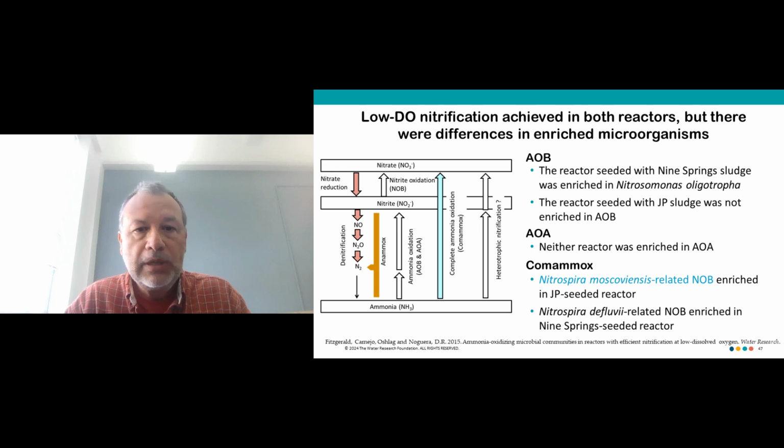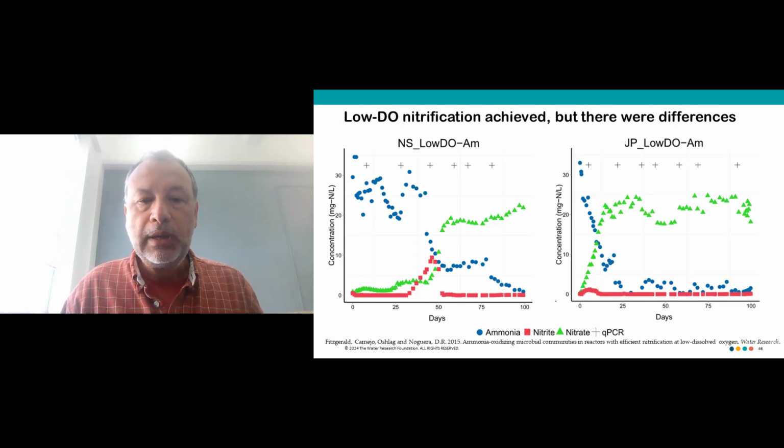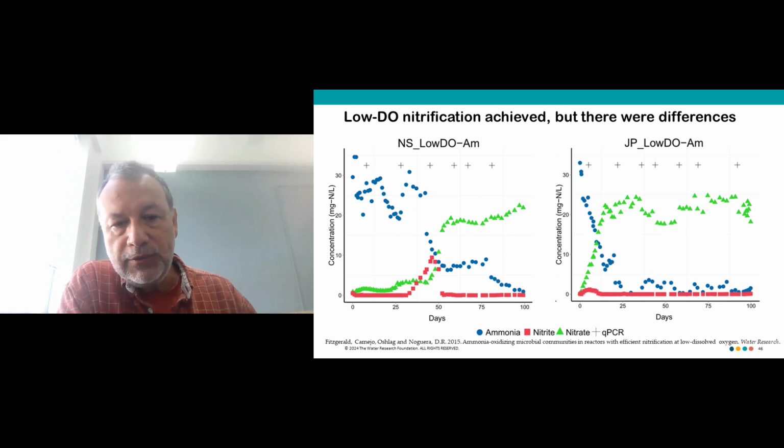Compare that to the other treatment plant, the Jefferson Peak treatment plant, where immediately, when we started the process, nitrification was occurring. There was nitrate already being produced. There was ammonia, or nitrite, in very little concentration, and then it was consumed.